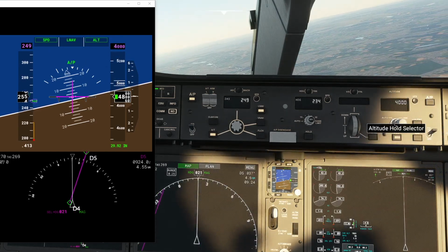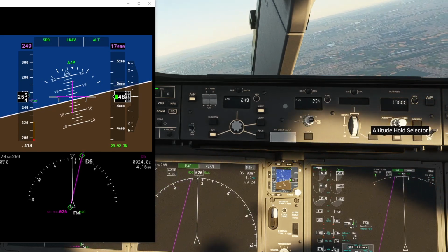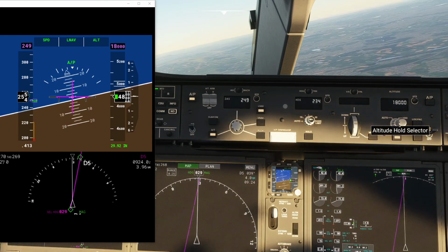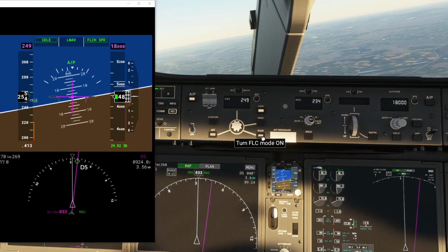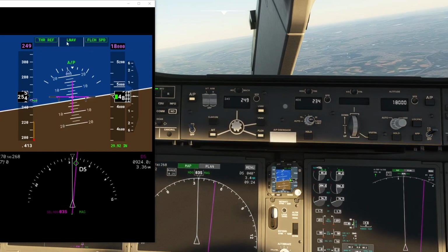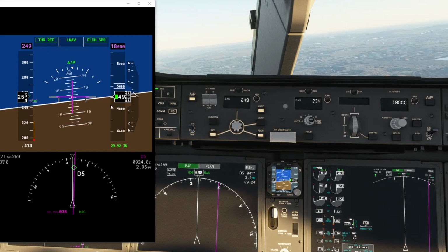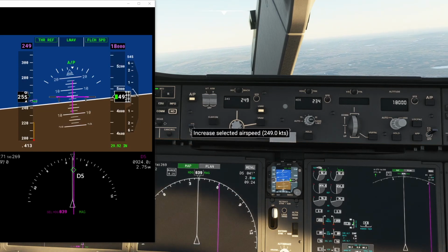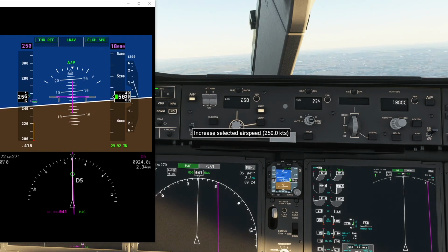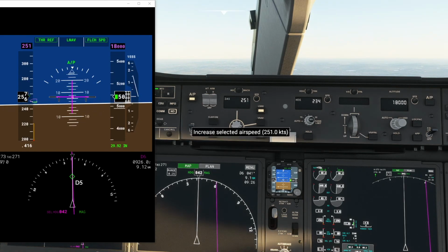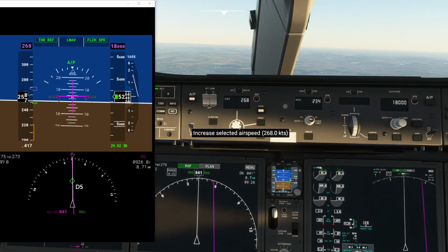It's a short flight today, and I would recommend around flight level 180 for our flight. So we'll set 180 in the MCP window. We'll verify it in the flight mode annunciator. Once we're happy with that, we'll click on flight level change. So we've got thrust ref for full power, flight level change speed in our pitch annunciation. And now we're at a safe height, we can increase to 250 knots. Normally we keep 250 below flight level 100, but we'll increase it now to 280 knots, assuming that air traffic control has given us permission to do so.